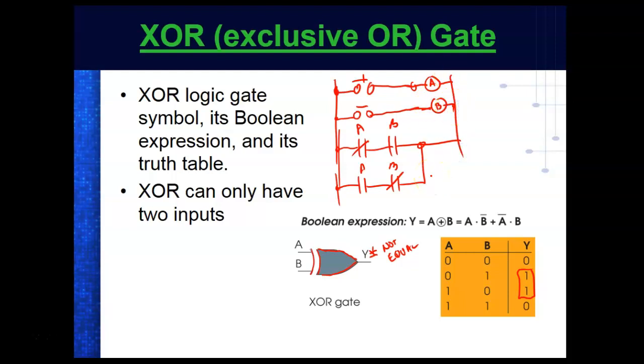So when you look at the contacts, you've got to understand something's controlling those contacts. So right now, my two inputs are equal, so these contacts would be in the state they're showing. It would get through with A, but it wouldn't get through with B. So I start off with a 0.